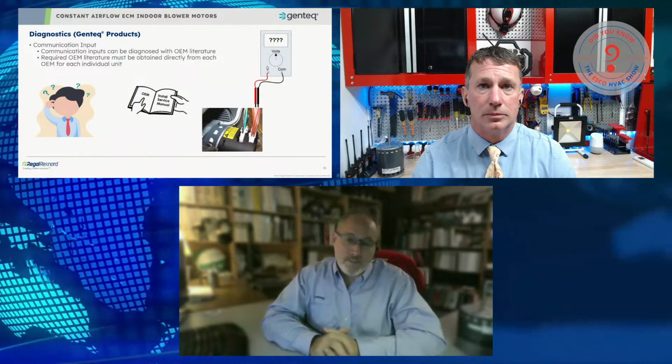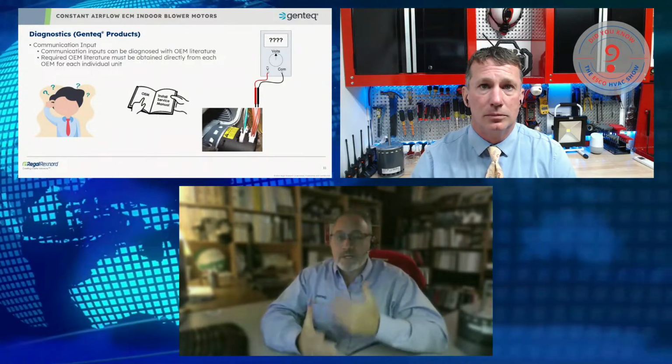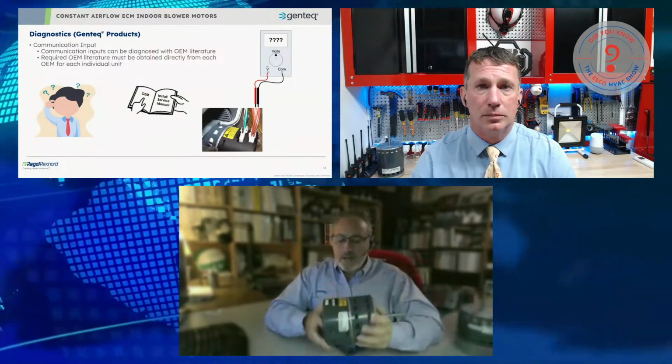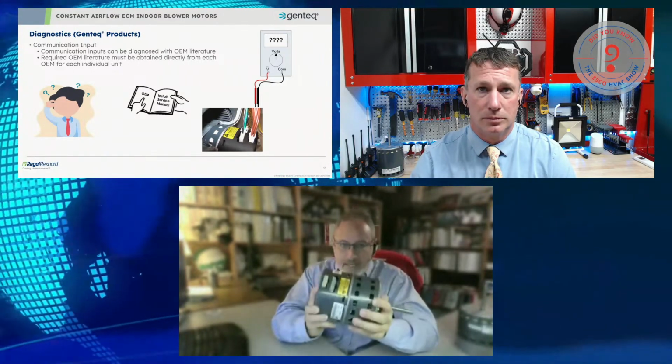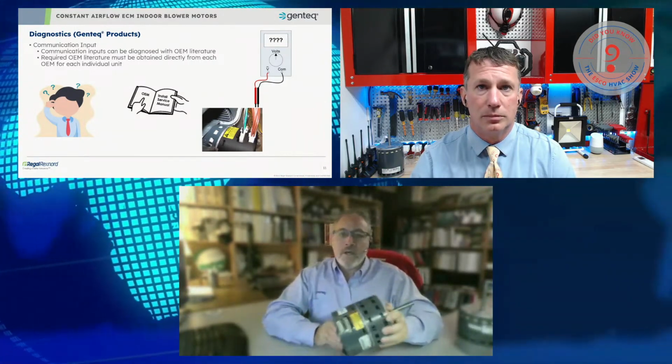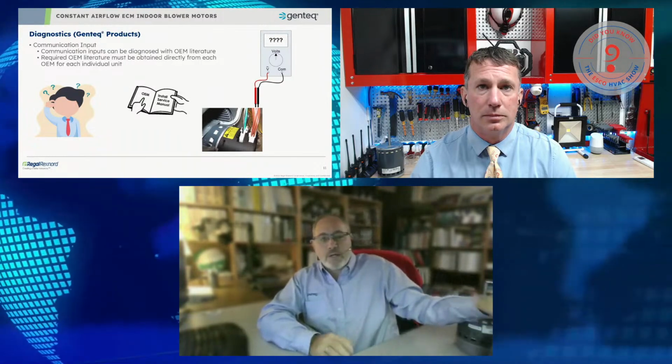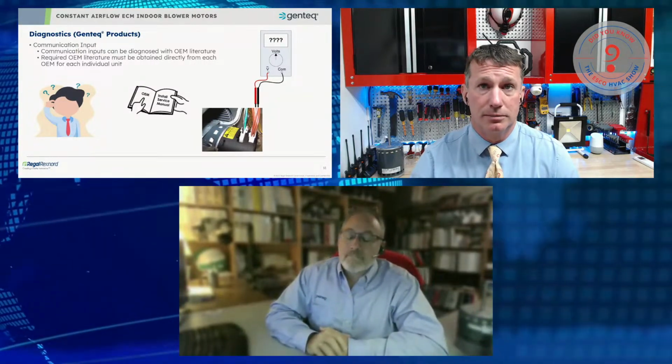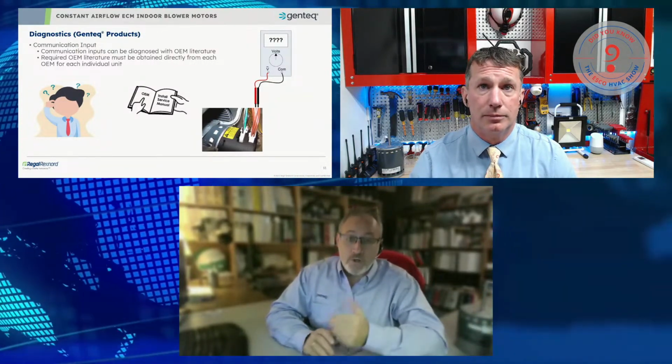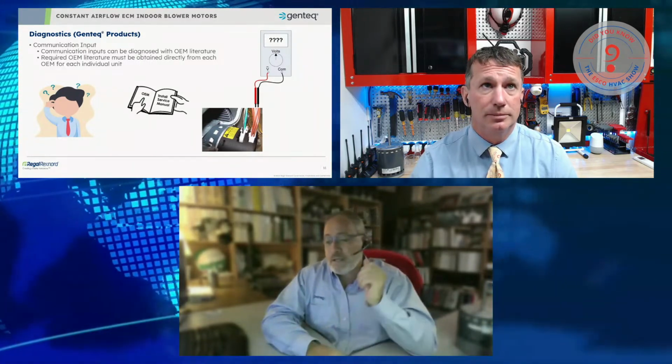That's the reason I like to bring those up: some technicians will think, well, I've got this motor and I see that same motor in 5 different OEM systems. Why can't I do that 9-volt battery trick on every one? And it's because of that unique program. Yeah, and some of those pins are not being used for particular functions. Correct. Or they're being used, but for a different function. Absolutely.